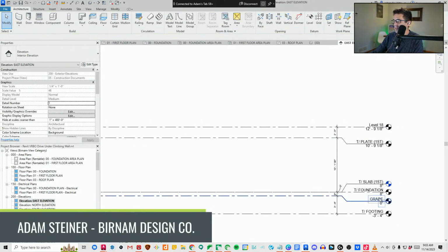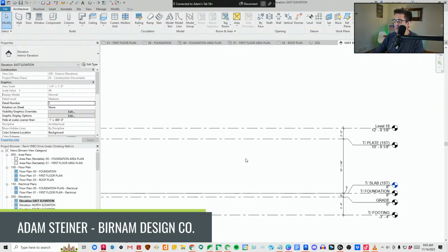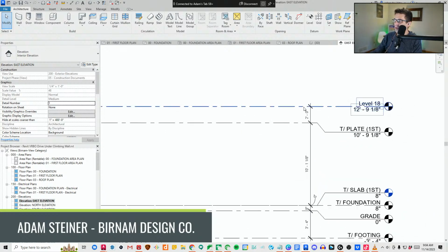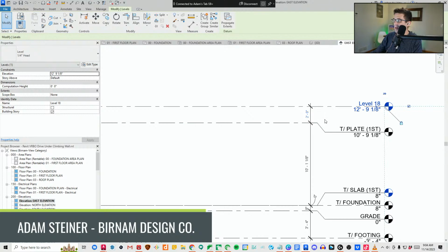Okay, so 10-foot main level will be a slab on grade. That's where the drive under garage will be, and then this will be. Let's see here. Let's do 20-inch floor trusses. It'll make it easier to build. This might be a little more expensive to go floor trusses, but it makes it a lot easier structurally. Yeah, so 20-inch floor truss that should get our span all the way across the garage, which means this level